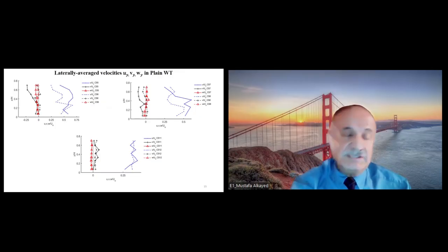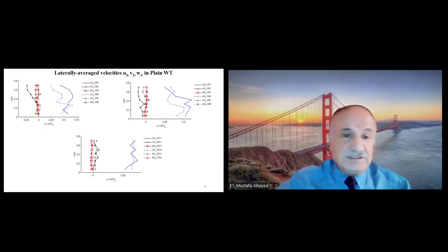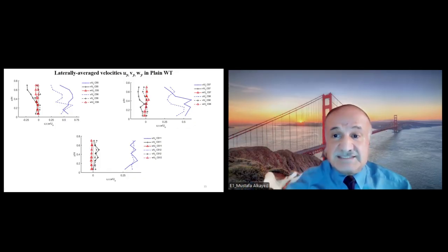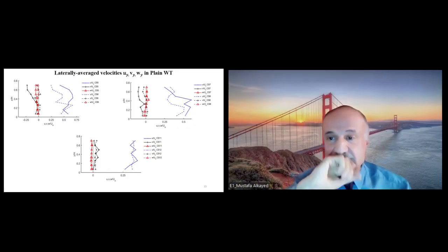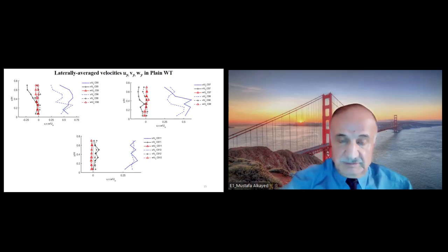So we can see this complicated shape, zigzag from the bottom to the top, and the velocity increases when we go up to the water surface. This complicated profile shows that the flow is fully turbulent and not stable, and we have the possibility of erosion of the earth channels in the downstream of this channel.